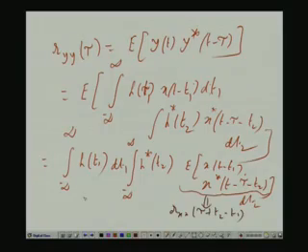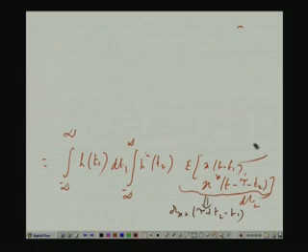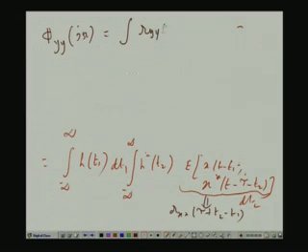That means we have to find the analog Fourier transform of r y y of tau, and this integral expression will come in handy, so I will just keep it here. So what is phi y y of j omega? It is the integral of r y y of tau e to the power minus j omega tau d tau, from minus infinity to infinity, the Fourier transform of the output autocorrelation. R y y of tau we have just evaluated a while back, given by this bottom expression, so r y y of tau has to be replaced by this.